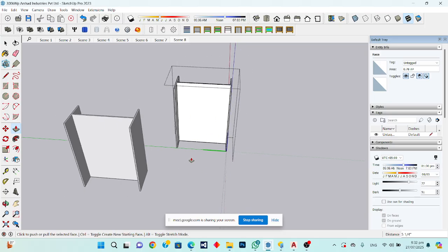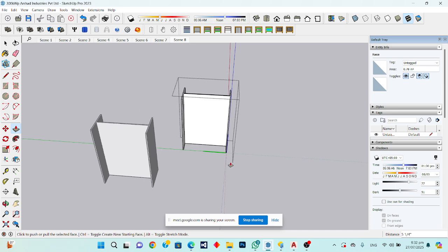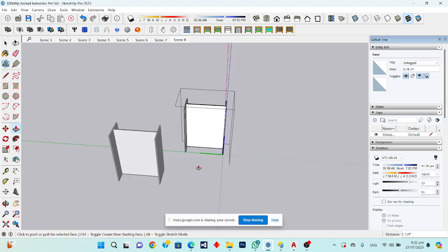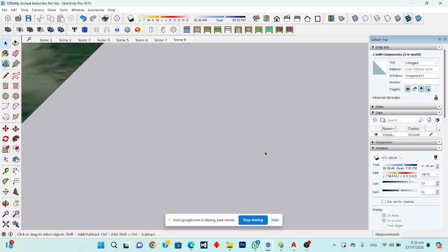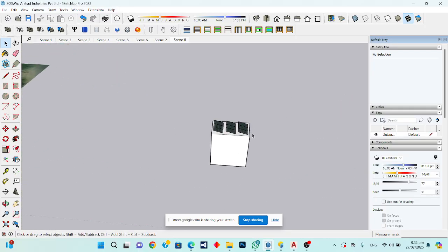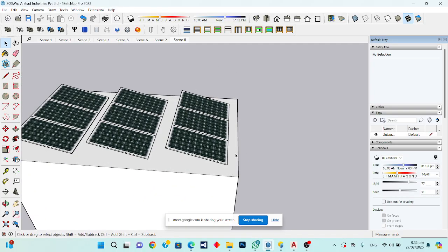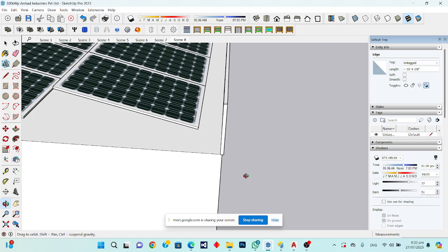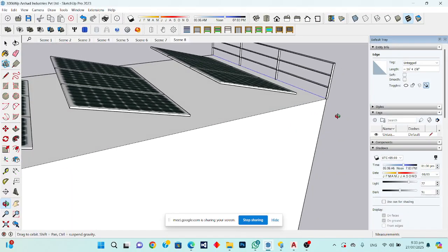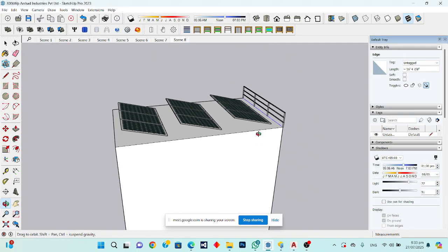So we have to make the component in the project formation. Basically, when we are using the same pole of the structure and the beam of the structure, we will give the same component name. So we have to make this as a manual function, but we can place the panel through the extension. Also I have this option of the fence, where in the ground mounted system we can use the fence system. So I give this, and you see that it gives us the fence of the structures. This is also through the extension.